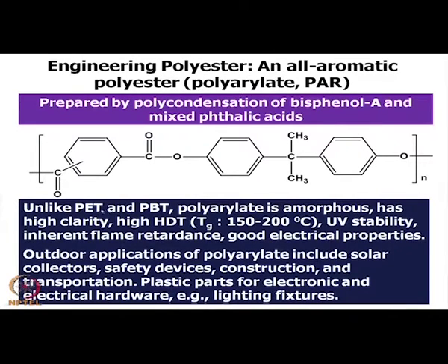Here, unlike PET, polyethylene terephthalate or polybutylene terephthalate, this type of polyarylate is amorphous and not crystalline, and shows very good clarity and provides high heat deflection temperature, and its glass transition temperature is quite high, 150 to 200 degrees Celsius. This range is given because of the presence of this mixed phthalic acid moiety. From one linkage to another, the glass transition temperature of the polymer varies.